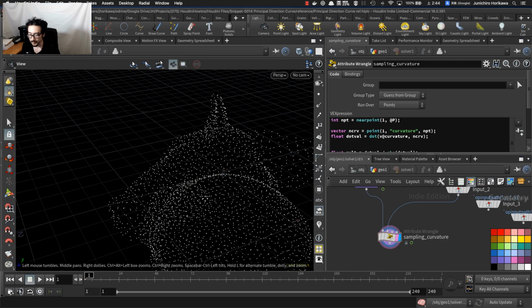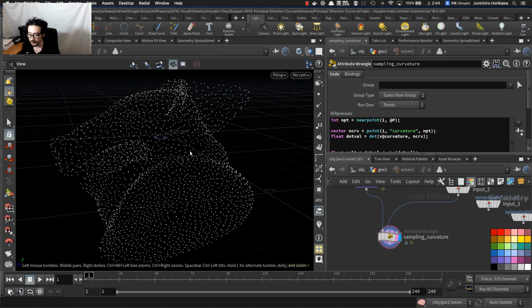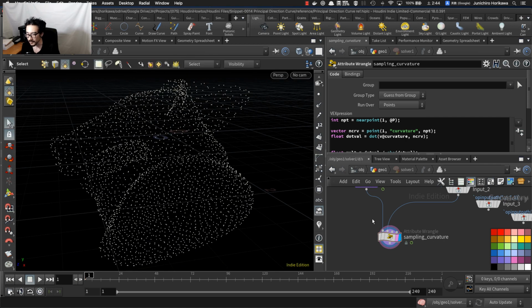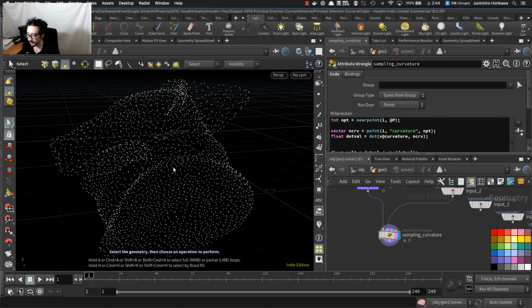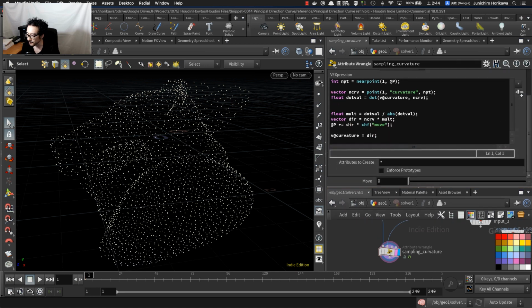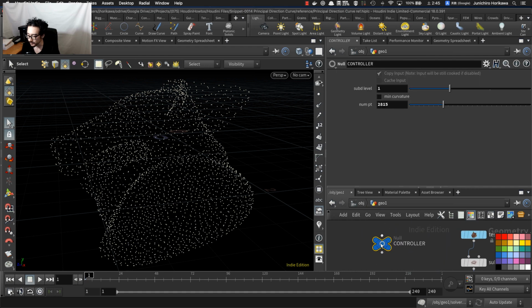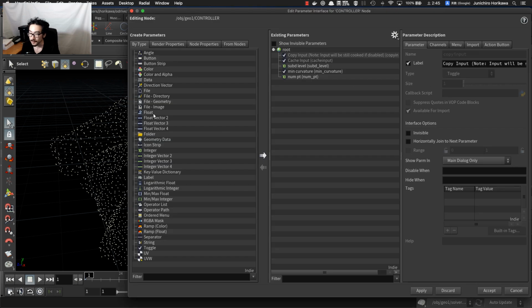And let's actually see the animation if the points are moving from each initial position. So let's get out of this subsolver, but before doing that, let's promote the parameter that we have just made here, this move parameter. I also want to link this parameter with the one inside the null controller, so let's go to the null controller and give additional parameters here.